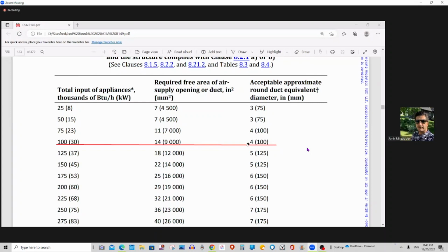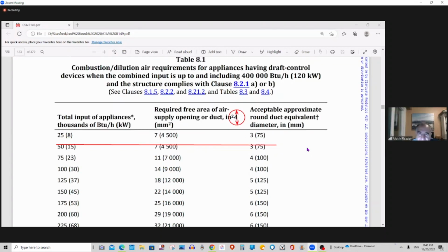When you have a furnace room and a hot water tank or another appliance inside that is natural draft, the inspector will make you make an opening and bring one pipe from outside, the flexible kind, for combustion air. Practical, 100%.